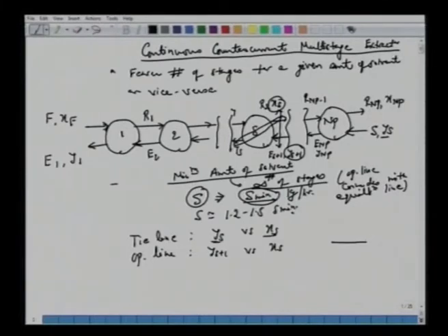All right. So now let's come down to this equilibrium curve here, and let's see how we address the minimum amount of solvent required. So A is the feed, B is the solvent, and C is the solute. And let's say we have the equilibrium curve like this. Now in general, the feed composition is fixed here. So we have F and we have XF denoted by this coordinate here. And let's say that the solvent is nearly pure. So we have S and we have this YS.